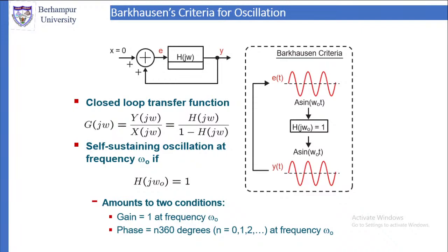So now this will act as a good amplifier so long as the feedback is negative, which means the phase of the feedback is 180 degrees out of phase from the output. The output of the amplifier and the output of the feedback circuit are 180 degrees out of phase. If they are in phase, then there will be growth. The oscillation will grow. That we will discuss later. Because the oscillation will grow, there will be oscillation.